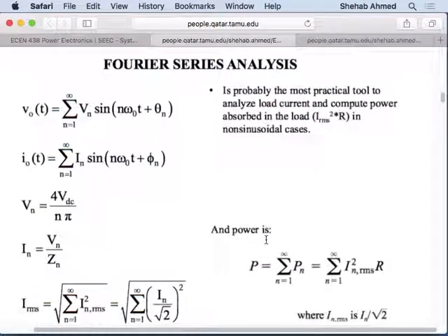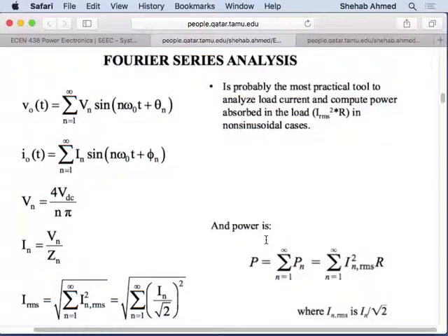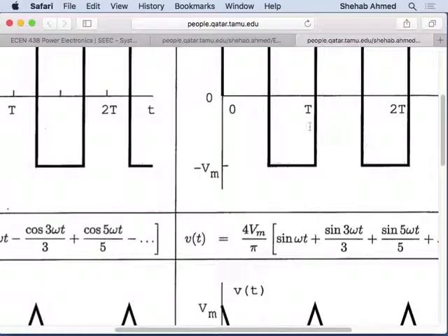And then we said, our objective is to finally get a nice voltage waveform that is as sine wave-like as possible, as well as the current waveform, right? Because that's our objective, of course, I have to do some analysis to look at where I stand now, so I can work on improving it, right? So the analysis will be based on Fourier series. We will not derive the Fourier series for the current waveform. We will go to the Fourier series for the voltage waveform.